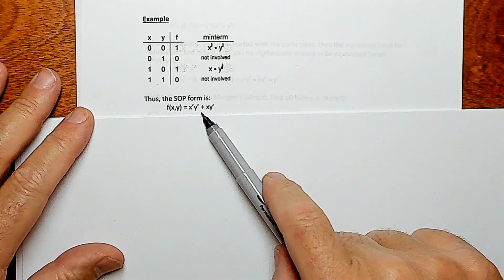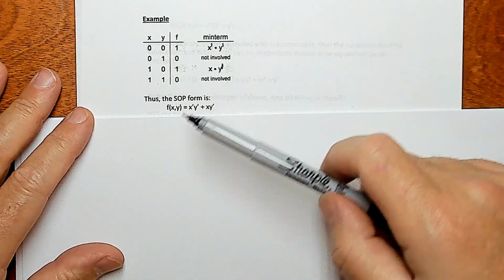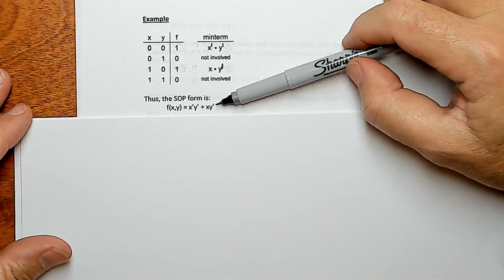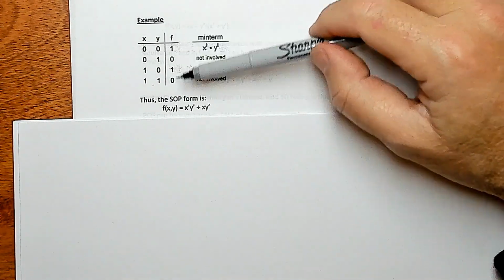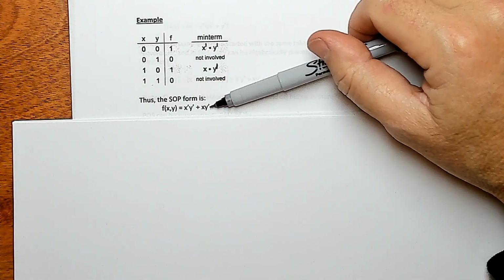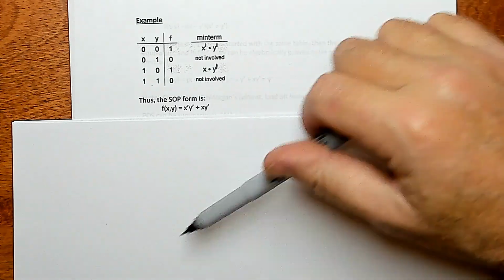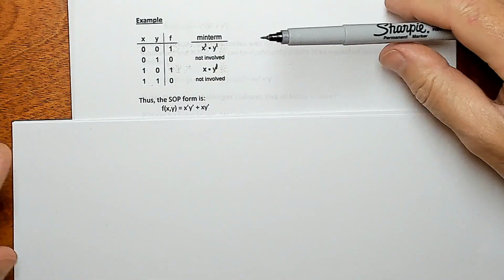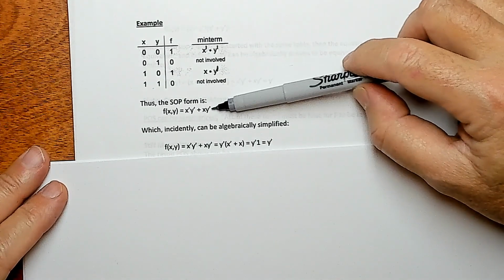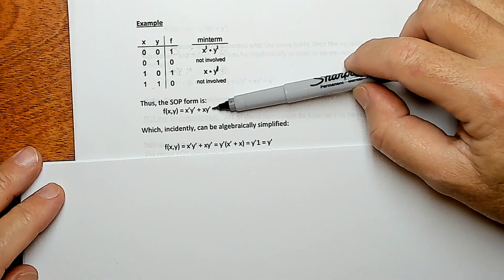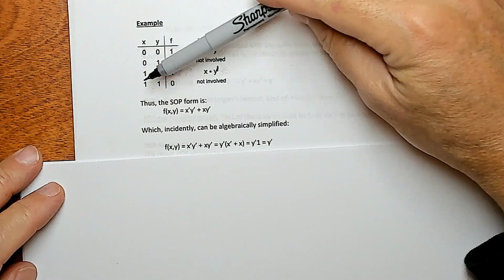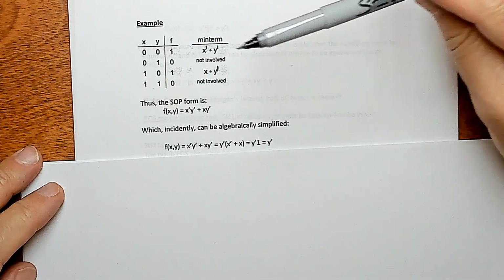Or really the or-ing of a bunch of andings, but it's easier to say sum of products. So this will produce this truth table here. You could prove it to yourself by building this truth table, starting from this equation and working backwards, and you'll see that you get this. So before we move on, this is what we call a sum of products form. It's product plus product, and if there were more inputs, there'd be plus product plus product. There'd be a whole string of them.